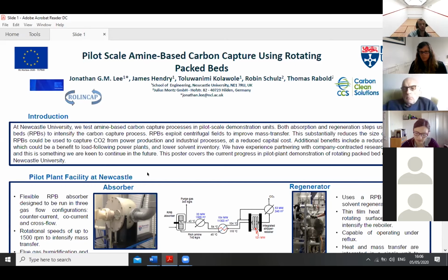Well, maybe, so my issue with ionic liquids, they're more physical solvents. So I would throw some water lean, BOL, some type of water lean bioorganic liquid, the stuff that PNNL uses in there, because they've got high viscosity around 150 millipascal seconds, and then the slow heat transfer, the slow mass transfer because of viscosity limits them. And once you have the centrifugal force, you could speed it up. So that would be huge. I would be very interested in that.